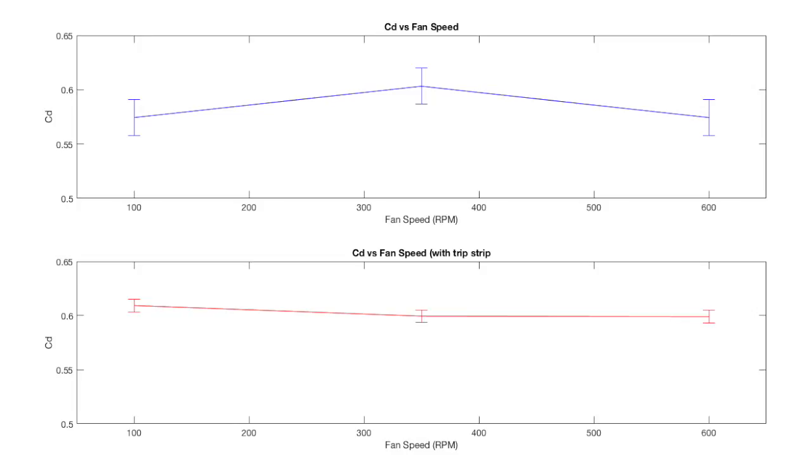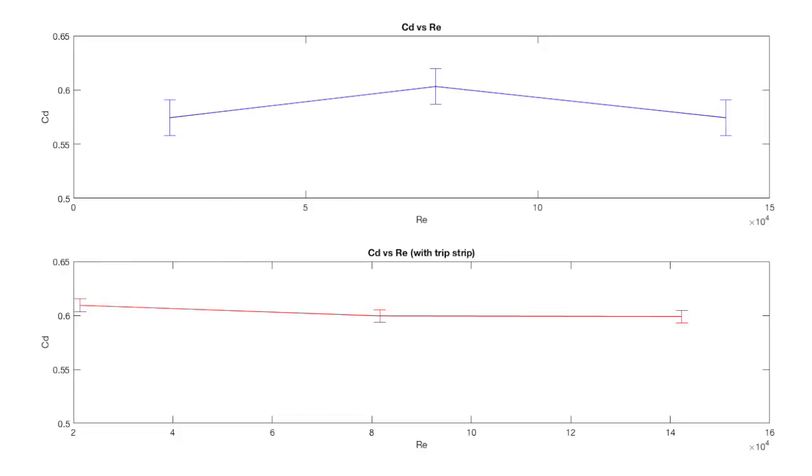In order to calculate the drag coefficient, a panel method was utilized. This method breaks down the cylinder into 24 equally sized panels, centered about each pressure tap. The pressure data recorded can then be used to calculate the average force in the direction of the flow at each port. Skin friction can also be calculated using the ambient testing conditions and average flow velocity. The addition of these two forces can be found to be approximately equal to the total force on the cylinder in the direction of the flow. From this total force, a drag coefficient can be found for each testing condition. This drag coefficient was then plotted against Reynolds number for both the baseline and tripwire configurations. Note that the error bars plotted represent the standard deviation and not the total error of the values.